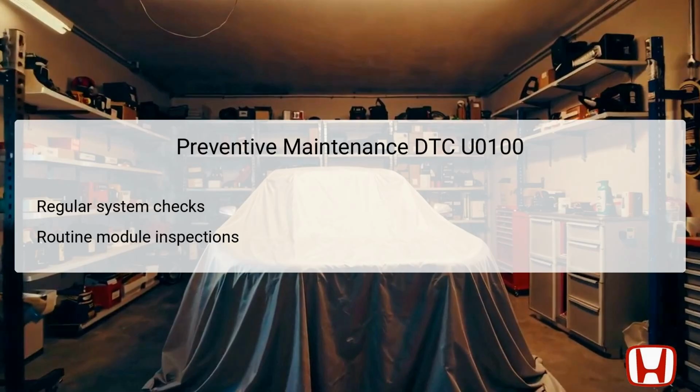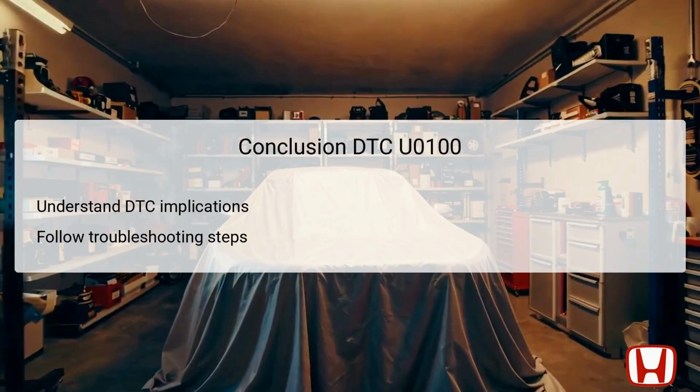In conclusion, DTC U0100 signifies a critical communication breakdown between the body control module and the engine control module / powertrain control module in the Honda Accord 2023 and newer models. Understanding the implications of this DTC helps technicians identify related issues effectively and avoid unnecessary component replacements. By following a structured troubleshooting approach, starting with power and ground circuit checks, one can often isolate the root cause swiftly.